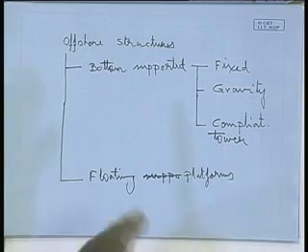So the difference between fixed and gravity is that in fixed, bottom foundation was done, whereas the gravity platform only sits of its own gravitational force, right? So obviously that calls for a requirement of heaviness of the structure, right? Many a time the legs are of concrete, right? And also another requirement of this gravity platform is that it needs fairly strong subsoil conditions, right?